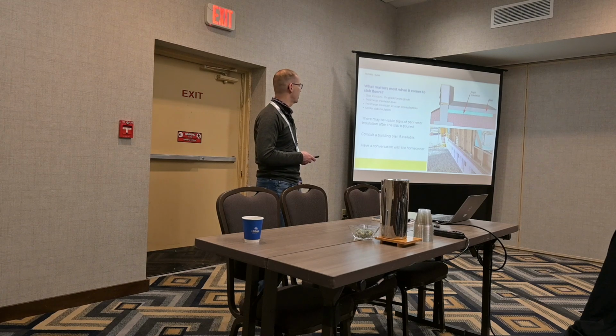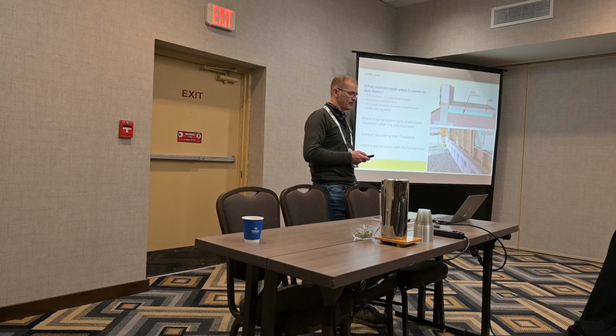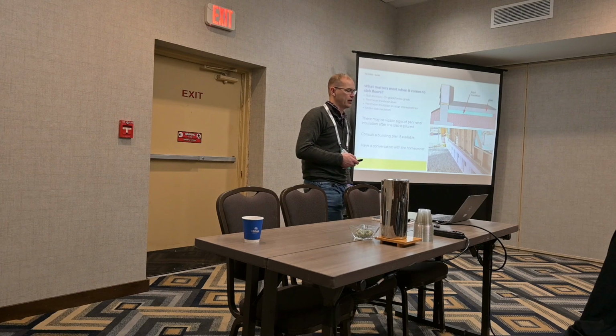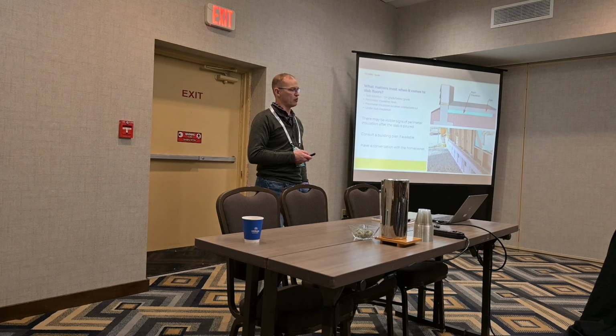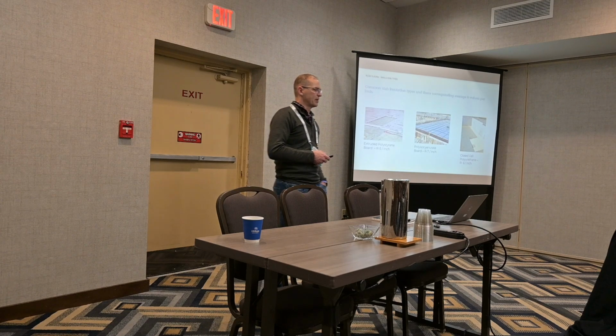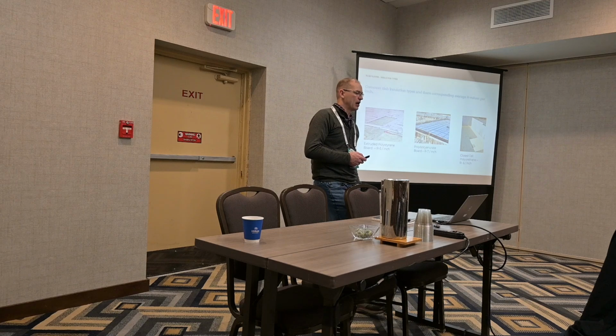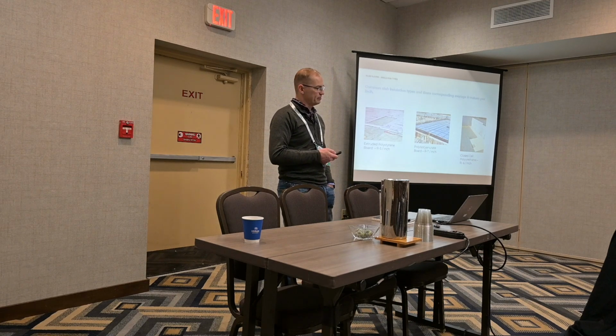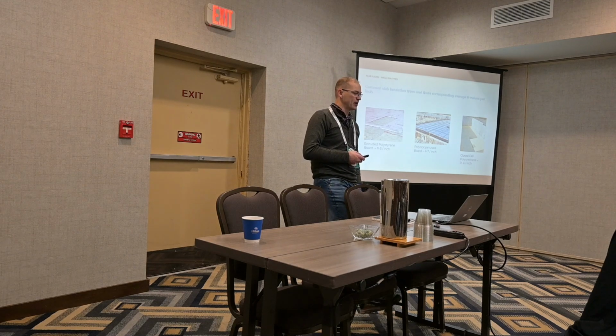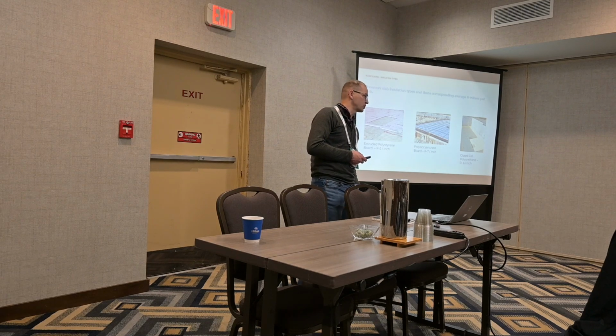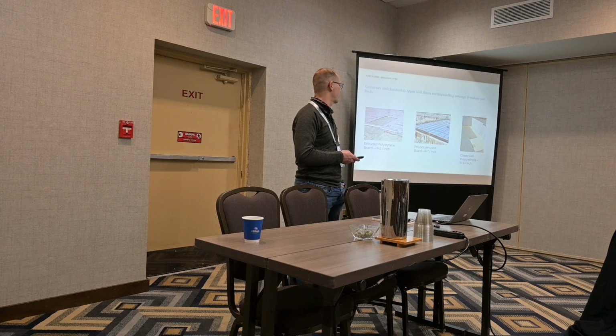Consult a building plan if available, and then have a conversation with the homeowner about whether they were there for construction or if they've done renovations. Common slab insulation types that correspond to average R values. Extruded polystyrene with an R5, the poly and closed cell poly are a little bit better with an R7, R6.